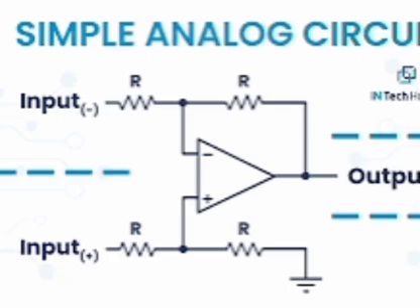Common emitter configuration. Base current amplification beta: when no signal is applied, the ratio of collector current to the base current is called beta. Beta equal to IC by IB. Also alpha equal to beta by 1 plus beta. Beta ranges from 20 to 500.